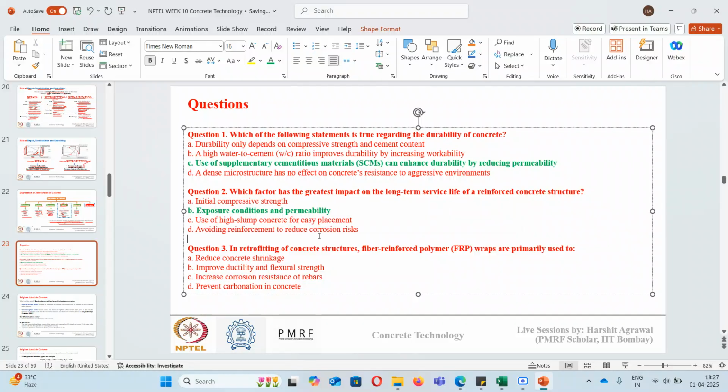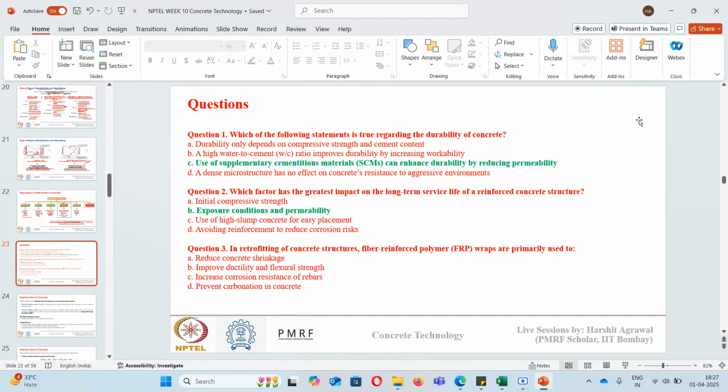Okay, that is true, but see, concrete can't take tensile load. And in practical application, there will be tensile load that also will be needed to be resisted, so that's why we are using reinforcement. Though reinforcement has a risk of corrosion, if we make the cover concrete very dense and impermeable, then we can avoid that risk, or delay it as much as possible. So reinforcement is a very crucial part of my structure in terms of practical application.